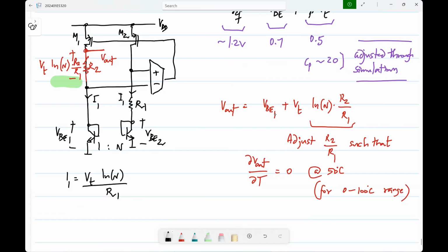So if we had equal VDS, source drain voltages, this problem won't be there. So how do we get equal source drain voltages for the two? Yeah, so very clear that I just put R2 there also. So if I do that, then I'm set, right? So then basically, I'll modify this circuit. You may still want to use a cascode for other reasons, but anyway, whatever it is, putting this resistor helps. Okay.